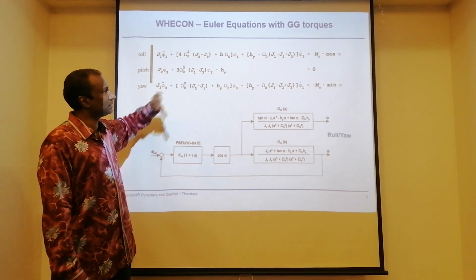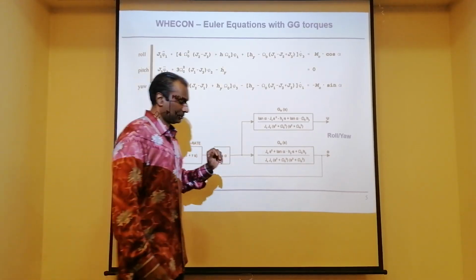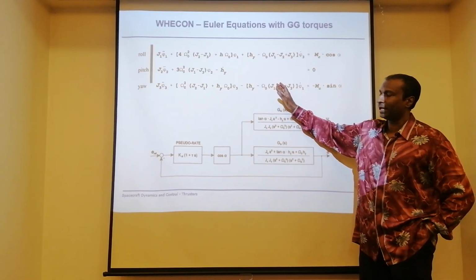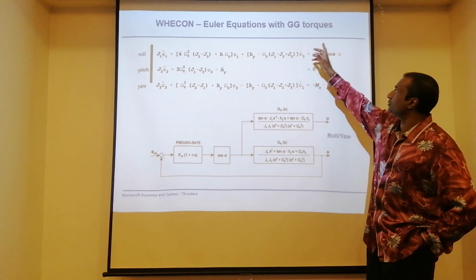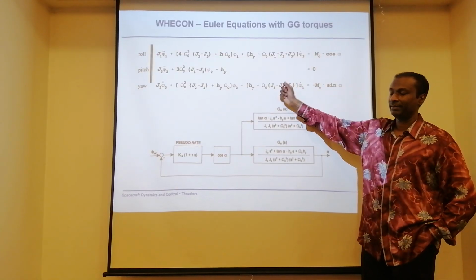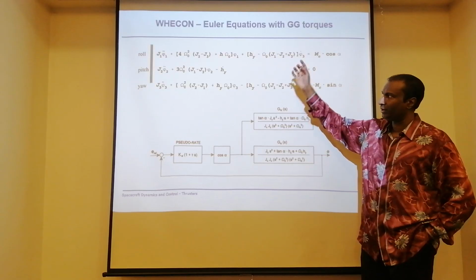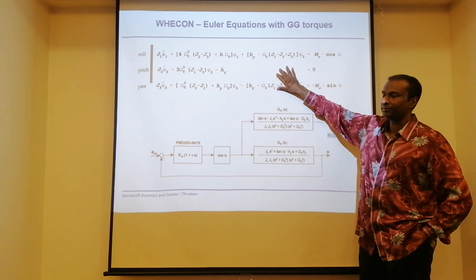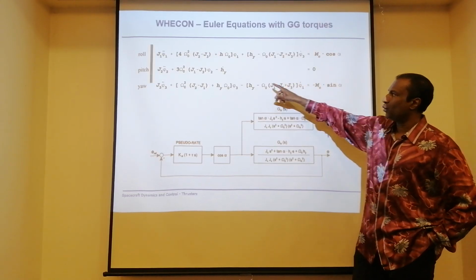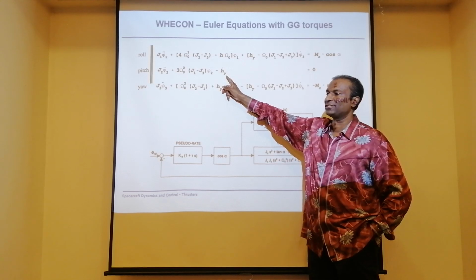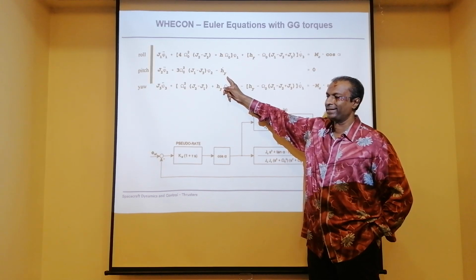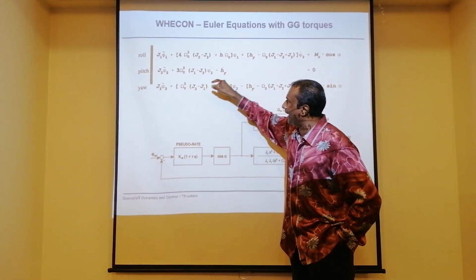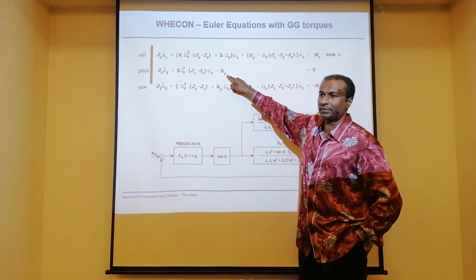Okay, here is what is a bit interesting. Now, remember this. This is the same equation that we have developed, and you have been using. This is with gravity gradient torque. That means, remember the gravity gradient component that we have inserted. This is including the gravity gradient component and with a wheel. And so H dot will be a torque. Momentum will torque. Which means that my pitch axis here can be controlled by my wheel.